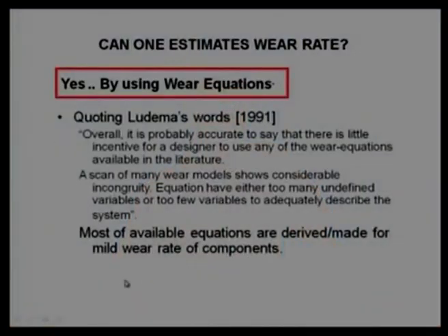So, using wear equations directly may not give complete solutions. We need to think from another angle. In addition, most of the available equations are derived for the mild wear rate of components. What is the meaning of that? If the wear rate is in the mild regime, then only can it be predicted. In the severe wear case, it cannot be predicted.